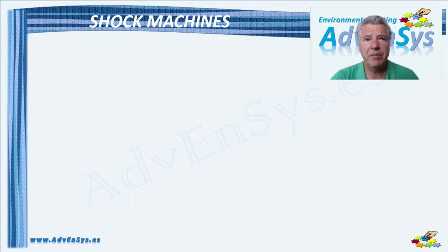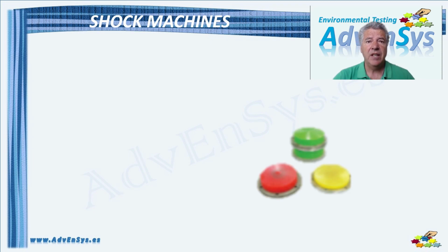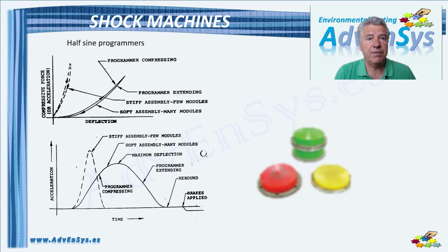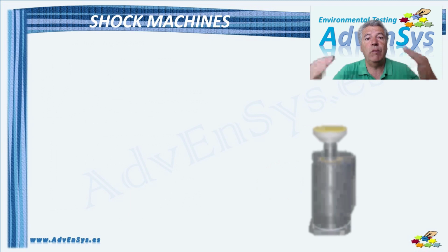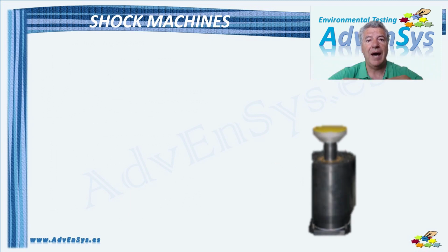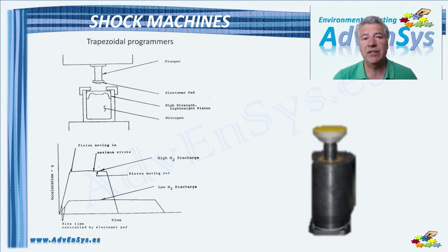For half-sine shocks, programmers are those of elastomeric materials with different rigidities and shapes. Depending on the stiffness and number of these, we get shorter or longer shock durations. For trapezoidal shock, the plunge impacts on a piston connected to a pressure chamber filled with gaseous nitrogen. The piston moves down quickly up to a point where it remains for a while, and then the rebound starts, generating the trapezoidal waveform. In this case, depending on the nitrogen precharge, the pulse will be high amplitude and short duration, or lower amplitude but longer duration.